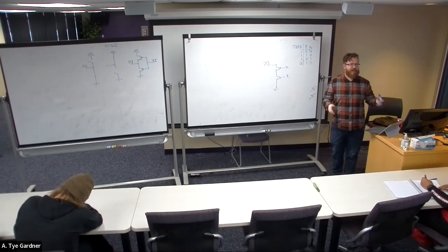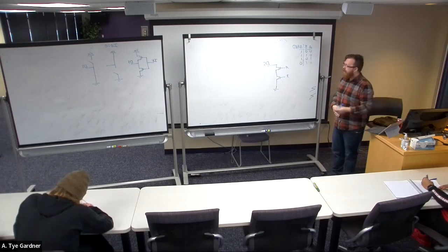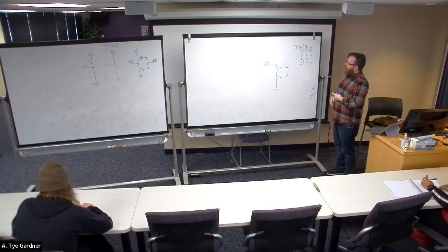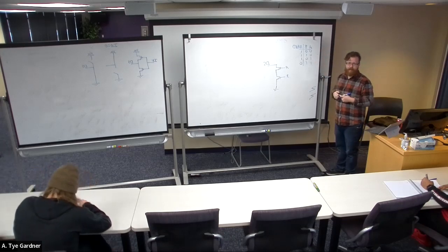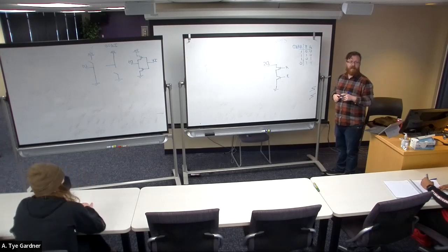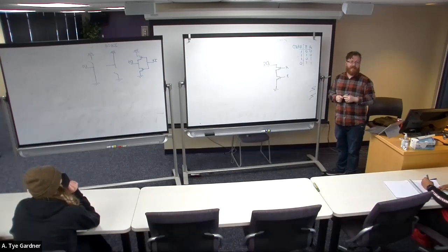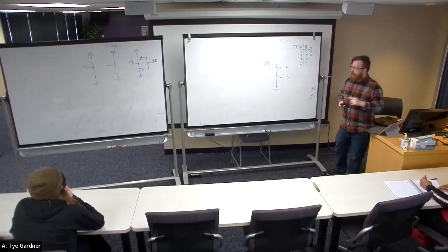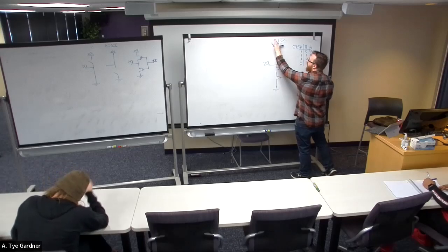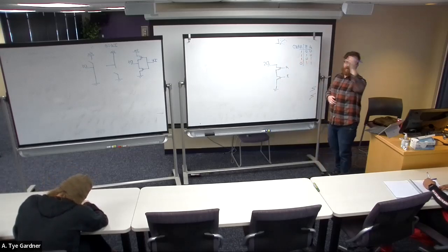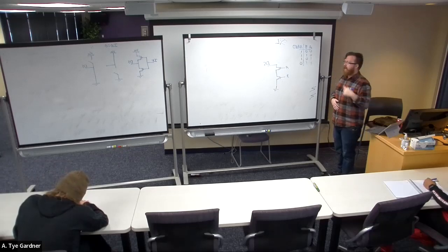So because we're talking NAND, let's think in active low logic rather than active high. It gets a little bit easier. And let's just say if A or B is 0, output a 1. So active low means zeros are on. If I have a signal S, and I say S dot low, that means this signal considers a 0 to be on. And active high would be a 1. That would be dot H.